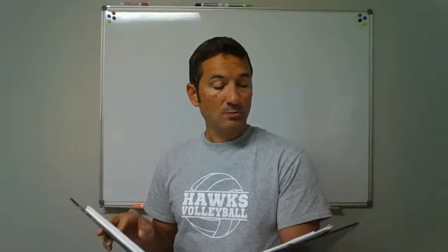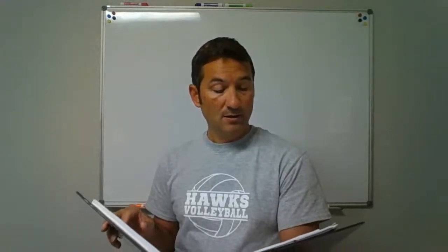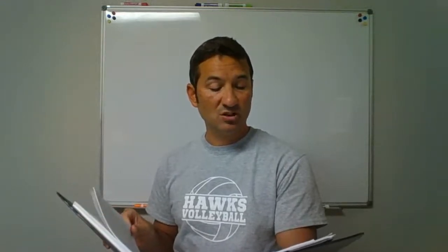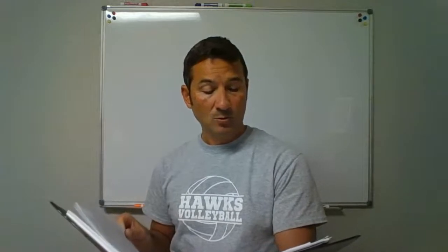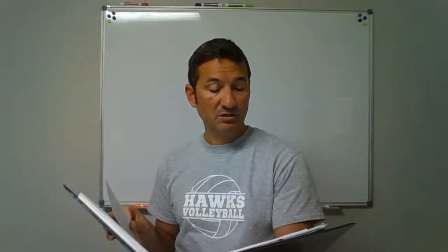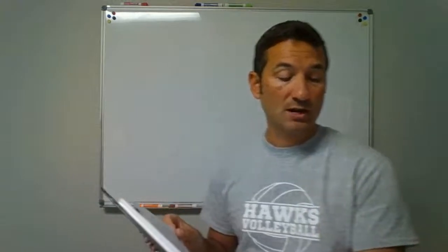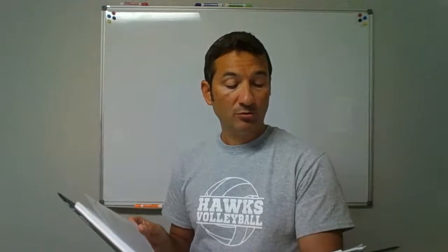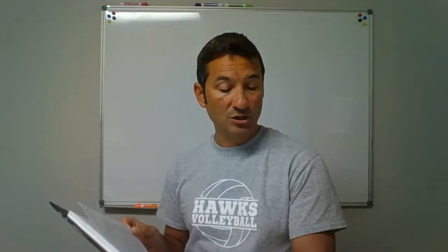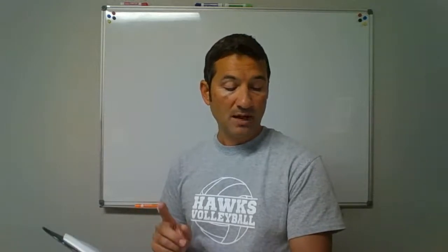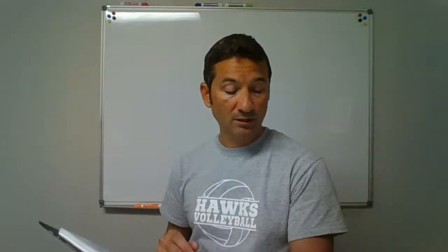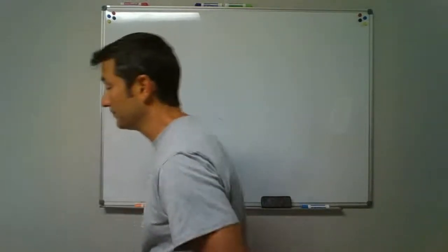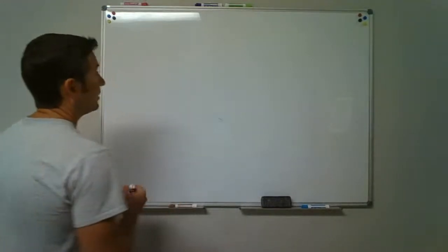Now, how do we protect it from stress and strain? Piping in a plumbing system shall be installed so as to prevent strains and stresses that exceed the structural strength of the pipe. Where necessary, provision shall be made to protect pipes from damage resulting from expansion, contraction, and structural settlement. Well, how about pipes going under footings or through foundation walls? Any pipe that passes within 12 inches of the bottom of the footing. Let me draw some pictures so we can get a visual representation here.